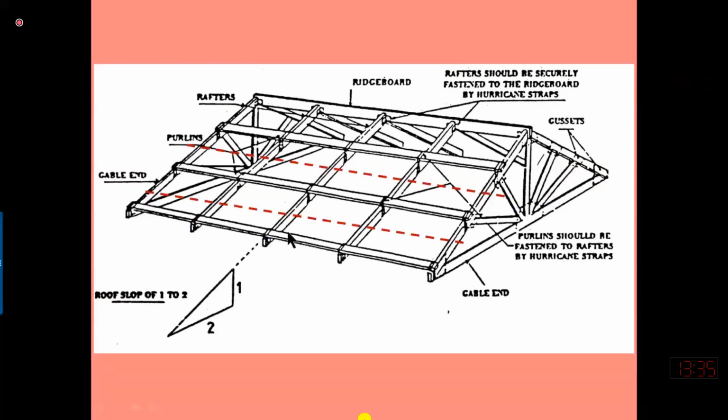Purlins are transversal beams. These are the beams which are provided perpendicular to the truss direction, connecting the panel points of two trusses. So one purlin is placed on the panel point of one truss and another on the panel point of the second truss. Actually, all type of loading is acting on the purlin. The trusses are only in contact with the purlin, and all the extra utilities, maybe roof sheeting and insulation board, are placed on the purlin.